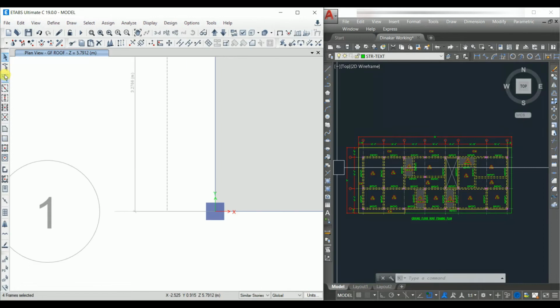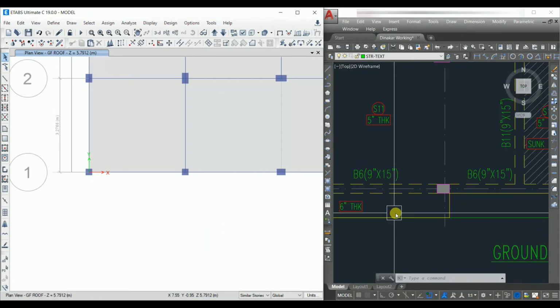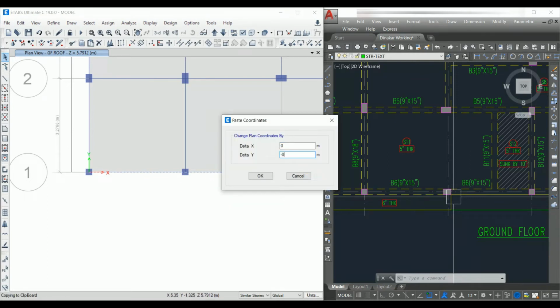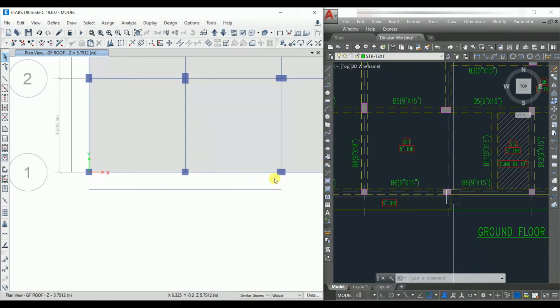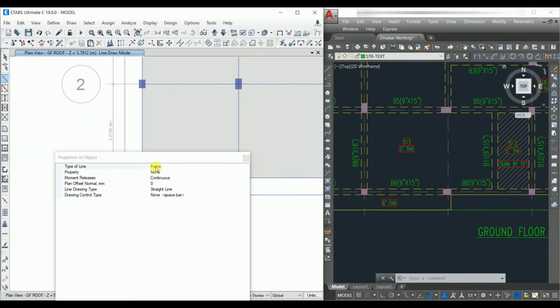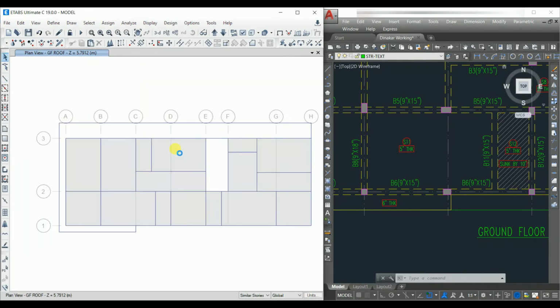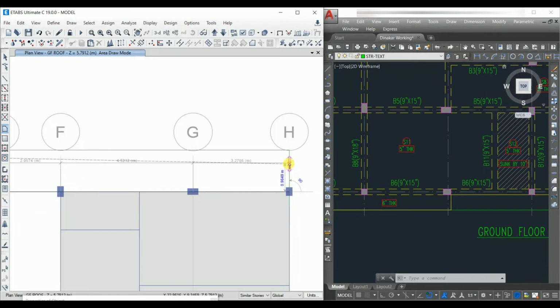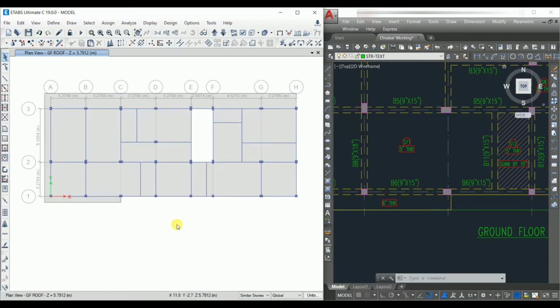And again, the projection is still here from this column. So let's copy paste this one. The y direction minus 0.6. OK, and add one beam here with the null property, and again let's add one beam here. That's all. Now let's fill the slab. So let's select this one and then choose the property as S125. So like this you can draw the slab. So it is done actually. The model is ready now. Let's check with the 3D view.